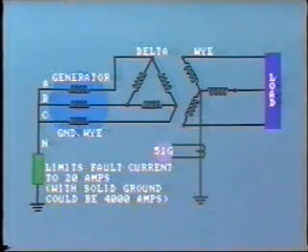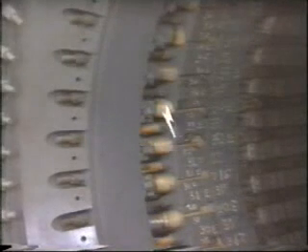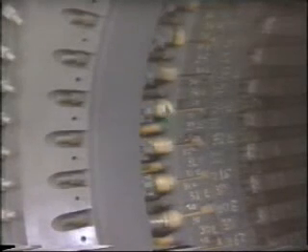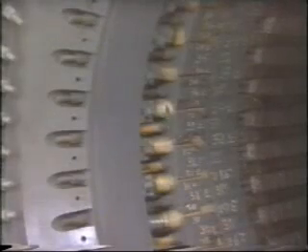But what is the advantage of impedance grounding? Well, by reducing the magnitude of fault current, we are reducing the amount of damage that it can do. For example, suppose the ground fault is in the generator winding itself. The very high fault current and resultant arc jumping from the winding to the stator laminations would probably burn and seriously damage the generator. We'll be discussing specific examples of impedance grounding in future tapes, but one point is very clear. When working on the power system, you must be alert for these various methods of grounding.